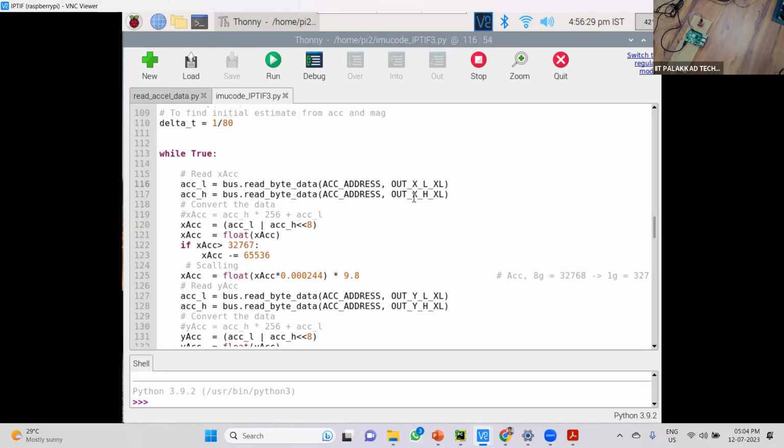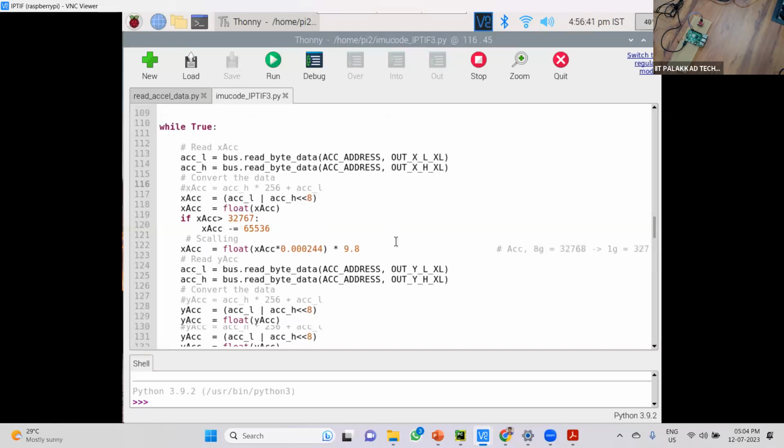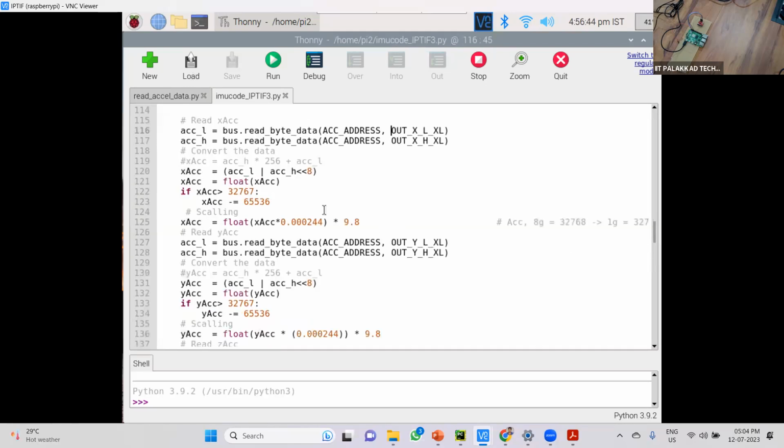I want two registers for taking data, because these registers are 8-bit registers only. My data will be 16-bit. Okay, but it has only 8-bit registers. That means my registers are 8-bit. So I want 2 registers, and I will do some left shifting or right shifting and all. I just adjust the data to make it into 16-bit, right?